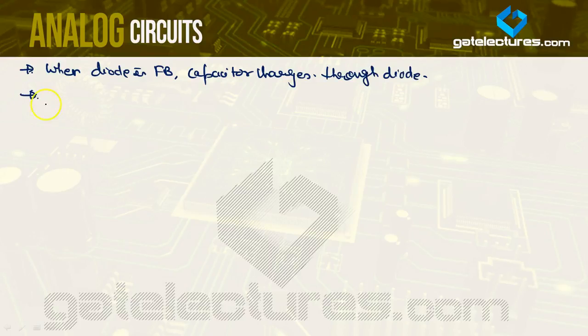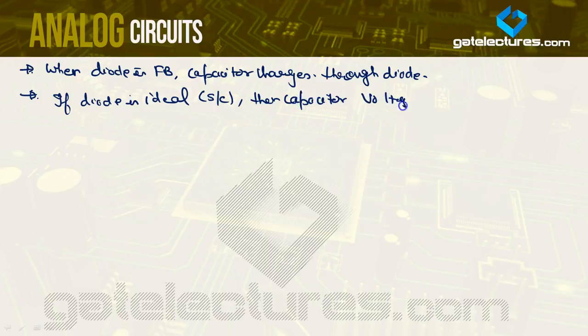Okay, so if the diode is ideal, this means it is short circuited when it is forward biased, and then the capacitor voltage Vc follows Vi. Otherwise there will be some potential drop across the forward resistance of the diode that we would have to take care of when we consider the diode to be non-ideal.